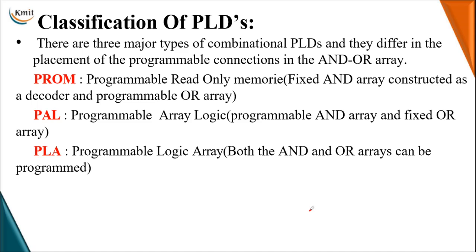Now, classification of PLDs. Basically these are categorized based on the arrays of AND as well as the arrays of OR, that is, programmable inputs of AND or programmable inputs of OR, versus fixed arrays of AND and fixed arrays of OR. These are classified into three categories. First one is PROM, second one is PAL, and third one is PLA. PROM is a programmable read-only memory.